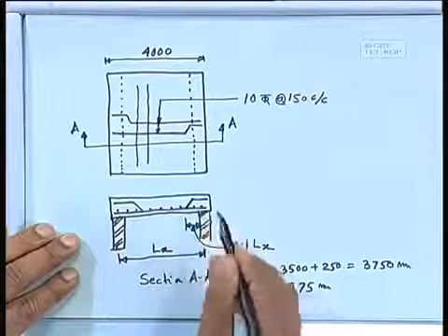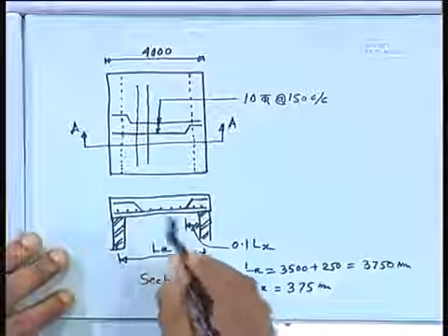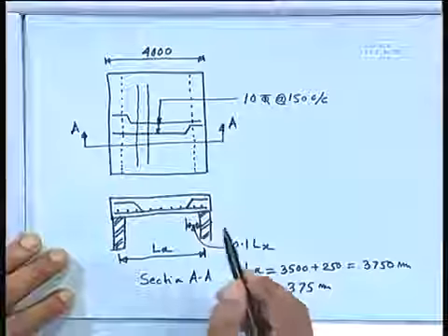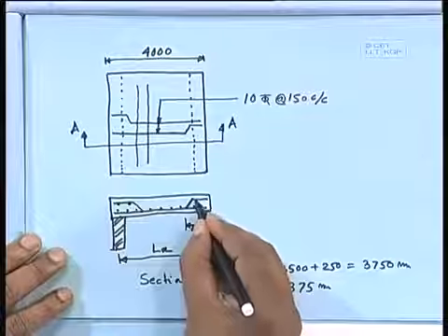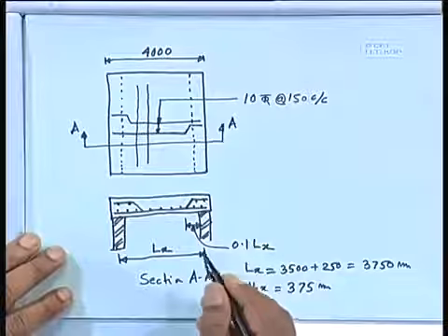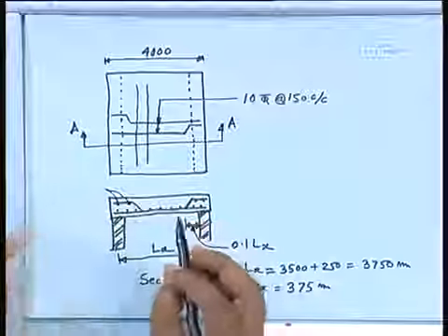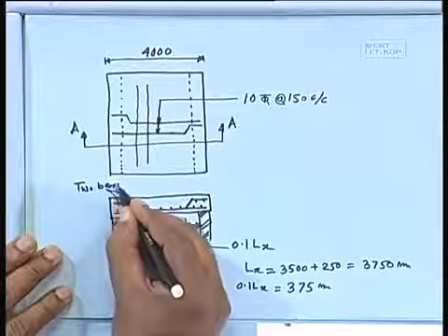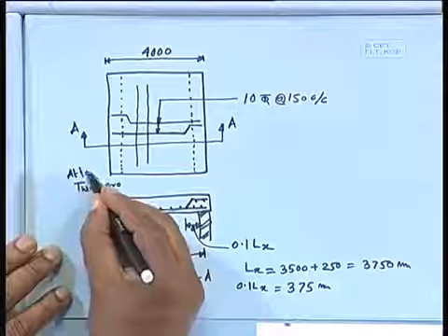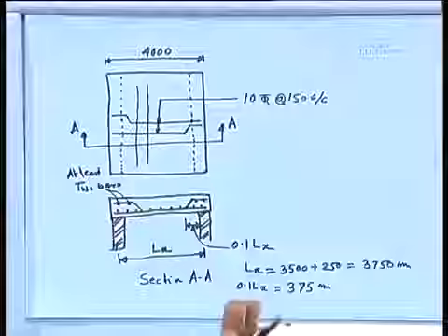We shall get it like that, because all the longitudinal bars in the other direction are cut, so we will get the circular ones with respect to the bar diameter. And similarly at the top also. Please note, we have to provide at least 2 distribution steel bars at the top to hold it. Even if the slab is small, you have to provide at least 2 bars.